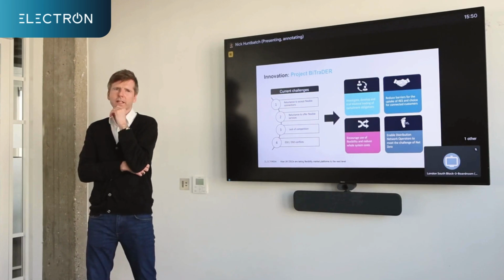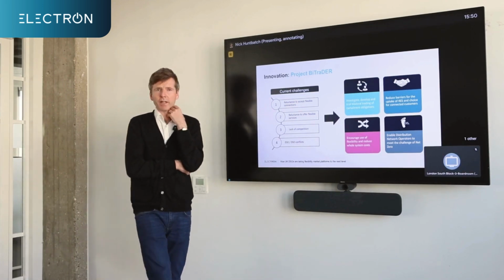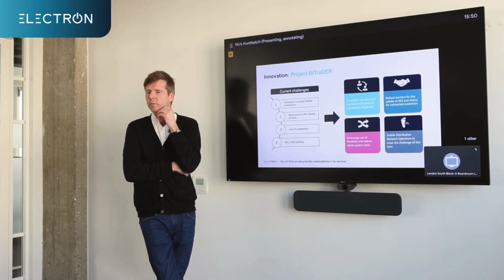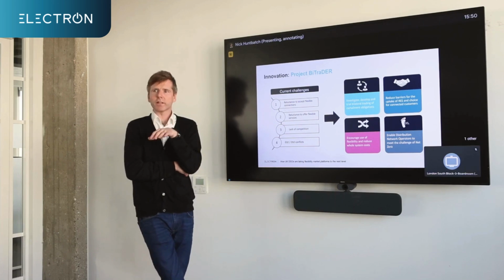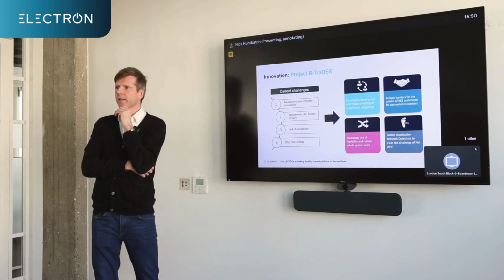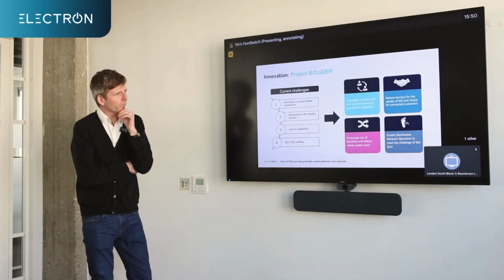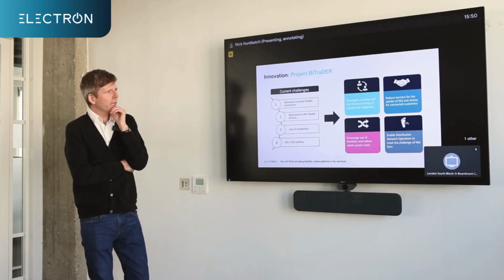There's a benefit to curtailment because people can connect quicker. Typically they'll say, you can wait for a firm connection. You'll never get curtailed, but it will take you a lot longer to get it, so you have to sit around waiting to connect your asset. Or you can accept a non-firm connection. You get connected a lot quicker, but you might get curtailed, which is bad. So it's one of those trade-offs.